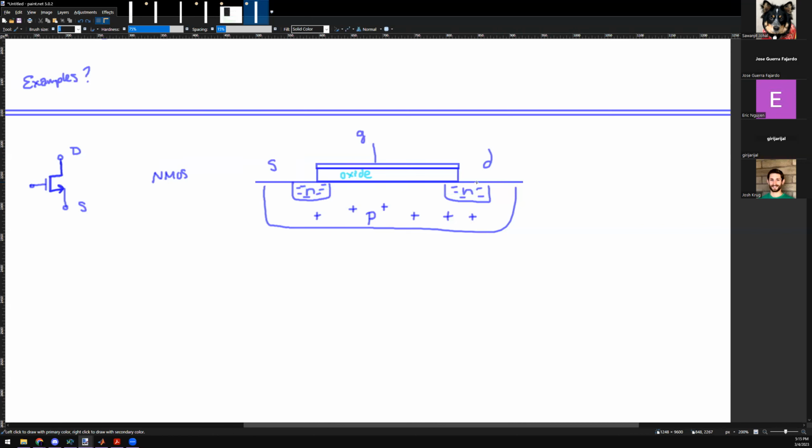Okay? Yeah. But meanwhile, if I apply some positive charge here, what happens to the positive charges here, or what gets attracted to this area? They repel, and then you get negative charges. Yes, exactly. The positive charges get repelled, and I start building up more negative charges here. And now the question is, is there a connection? Yeah, there's a connection. Positive on the top and negative on the bottom. So from the negative side of the source to the drain, is there now a bridge that connects them? Yes. So can electrons flow? Yes. Correct. Electrons can flow.